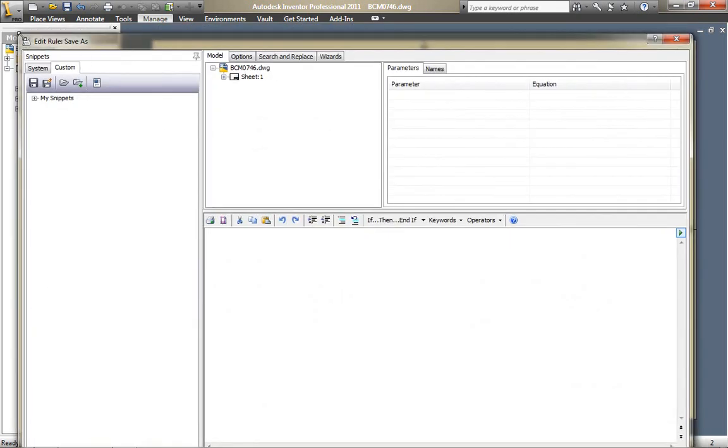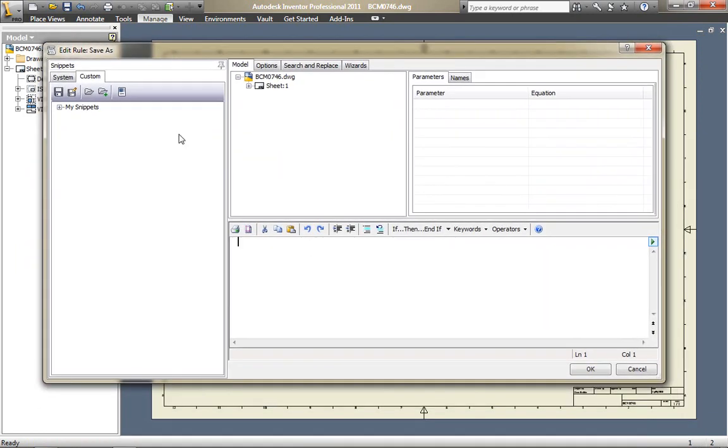Now, rather than having to use the Save Copy As tool manually for each file format, we can use iLogic, which is embedded directly into all the Autodesk Inventor Suite products, where we can add rules-based design automation. For those that have used iLogic before, you'll know that you can very quickly and easily build rules based on what you want to automate. You don't need to have a lot of knowledge of Visual Basic or those kinds of coding tools. We just use the iLogic interface to quickly and easily write, in this case, just a single line of code to ask iLogic to save the JPEG file when we run this rule.